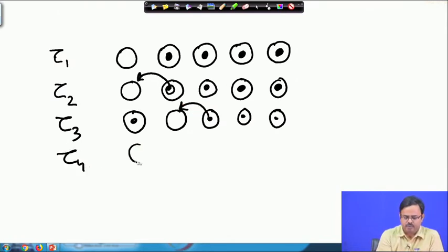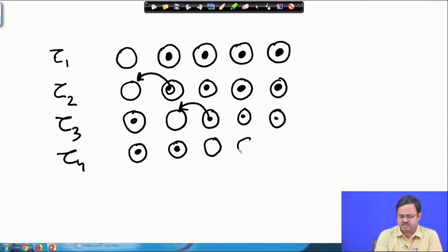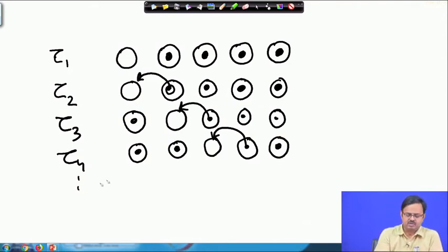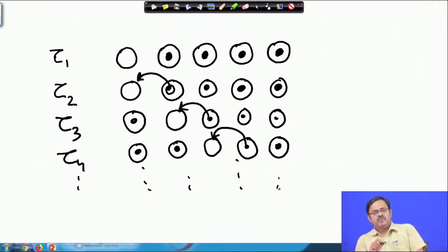At time 4, this is full, this is full, the third one is empty because it has lost its electron, and an electron from the fourth atom will try to go in and fill up this void. And this is how the motion continues. So, this is the mechanism by which, what have we seen now? We have seen how the hole has propagated from the first atom to the fourth atom.